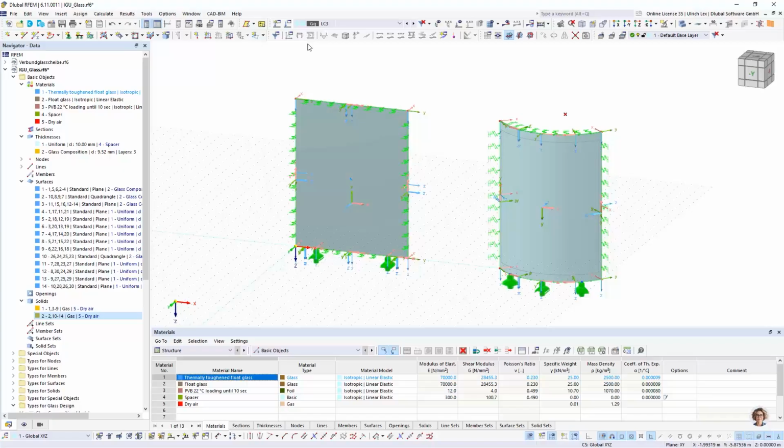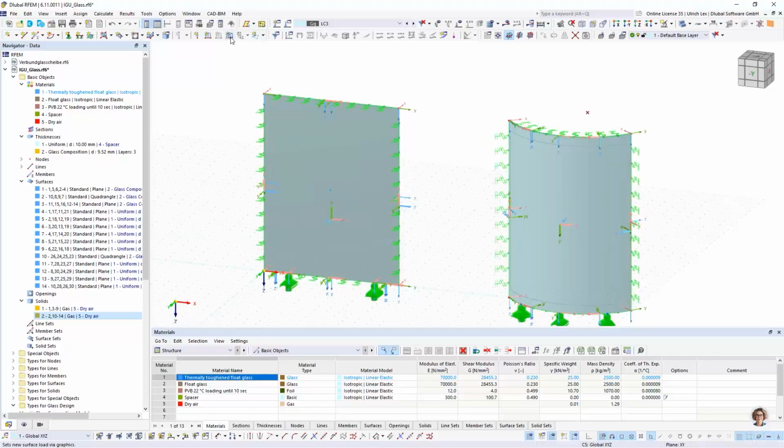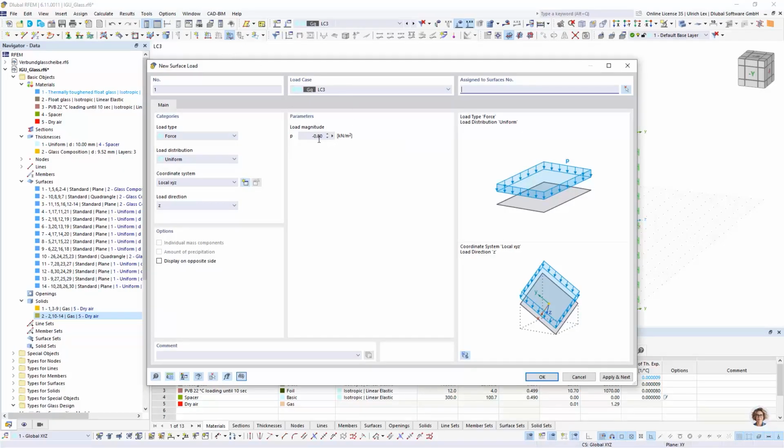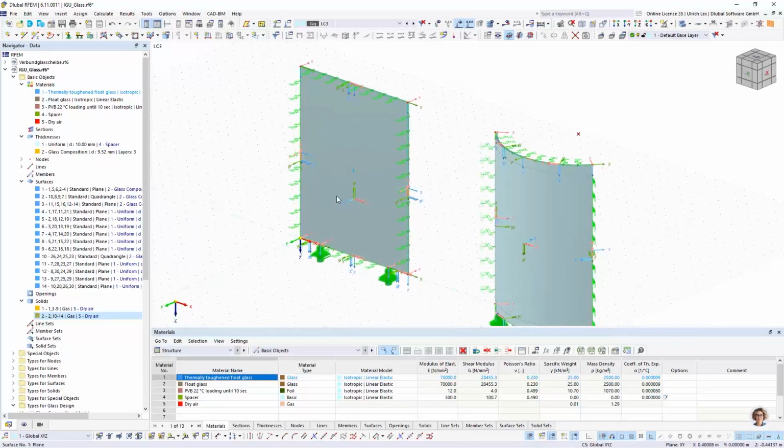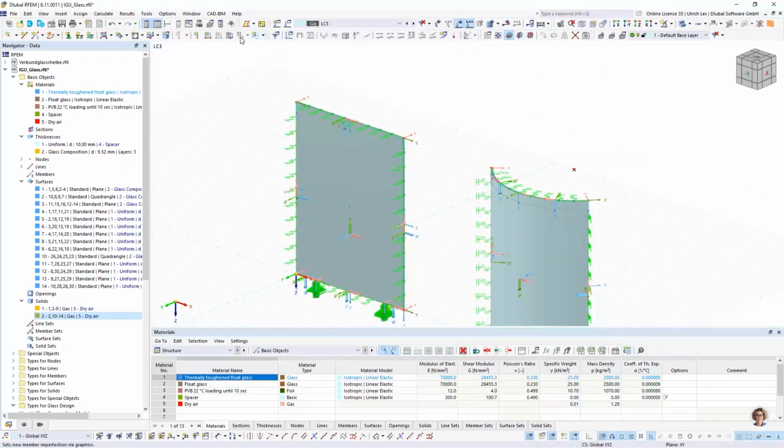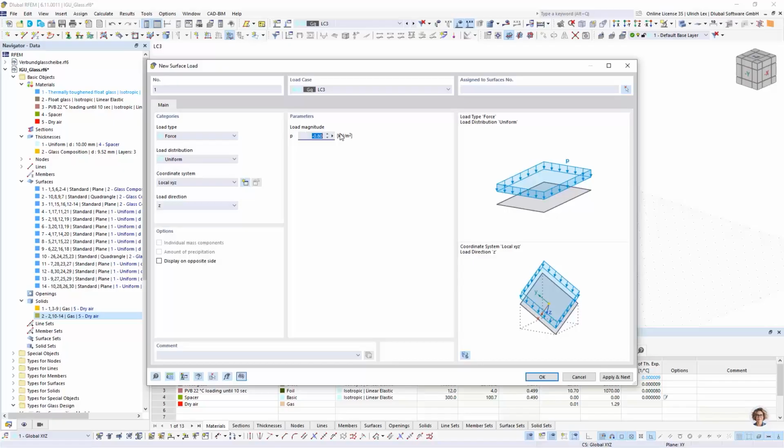This value of 600 meters, I can recalculate it to a surface load with the factor 0.012. It's given in the literature. You can find these formulas for it. So I choose a surface load with 7.2 kilonewton per square meters, and this is acting now